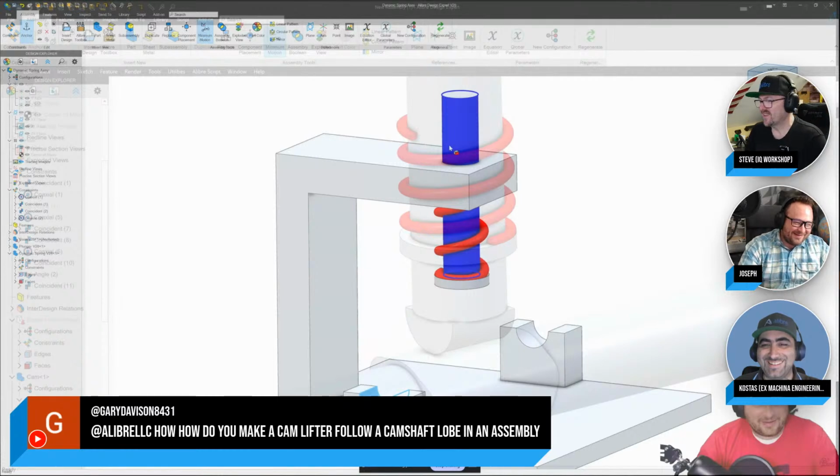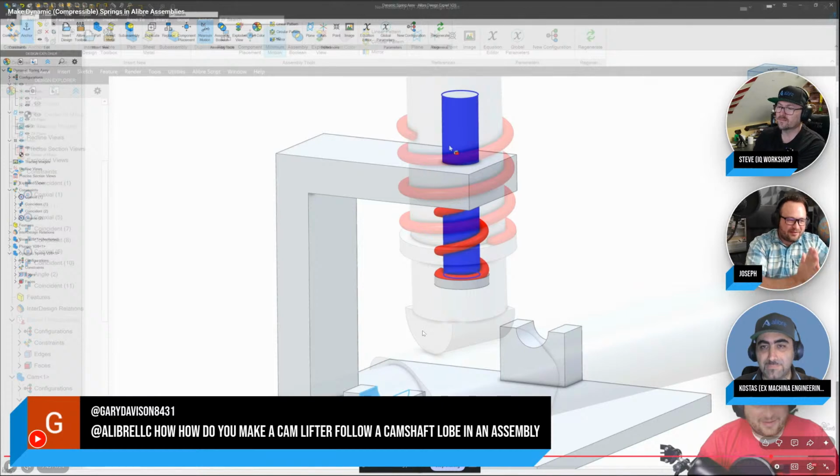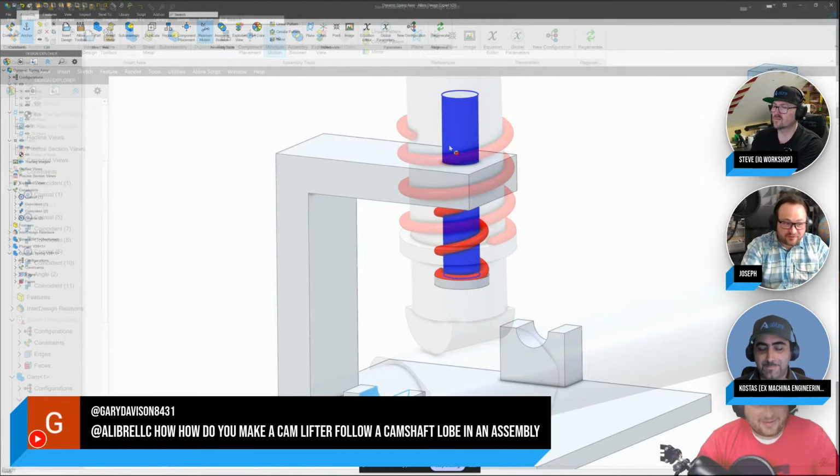I get it. In this, basically what we do is a design in context, right? So we have this cam lifter, and then we have this part that we make in the context of the assembly, and we say the sketch that defines this arc is tangent to this lifter. Now, this may actually apply to that S-shaped slot question too.